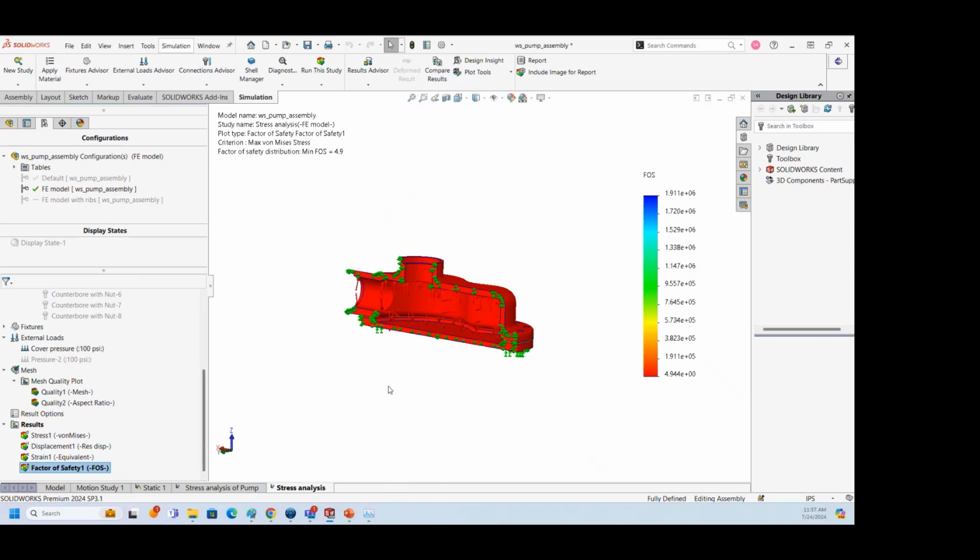So you have to define the material property, the interaction, whatever you have, and the loading condition, that is the real world condition. Once you do this, make sure you have a good quality mesh, and finally you can interpret the results with respect to the stresses. So predominantly, when you are dealing with linear static analysis, you will be mainly focusing on how safe the model is, whether it is going beyond the yield or not.